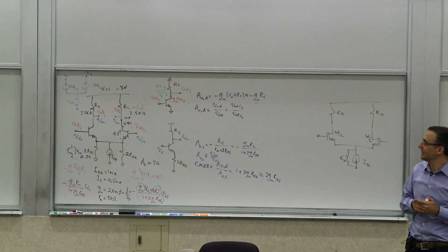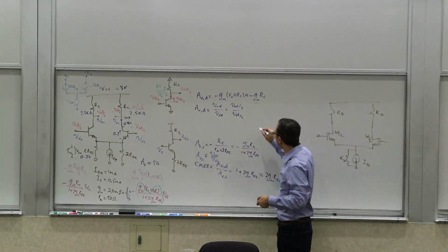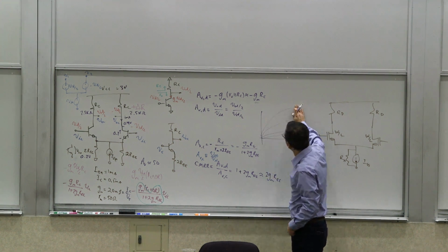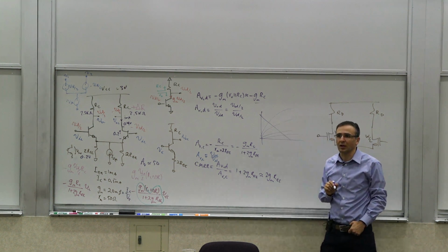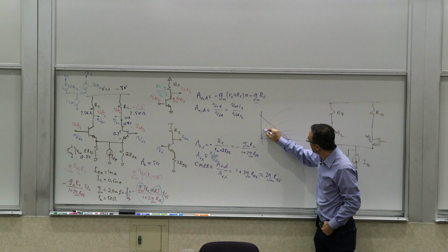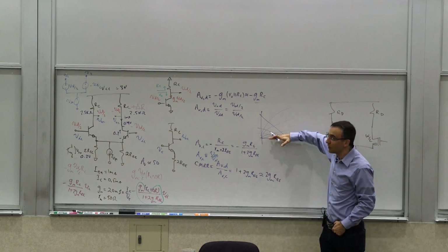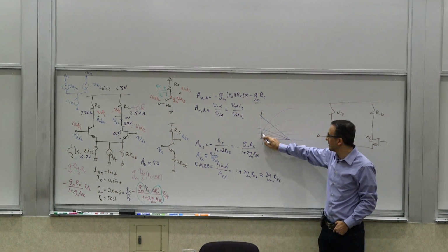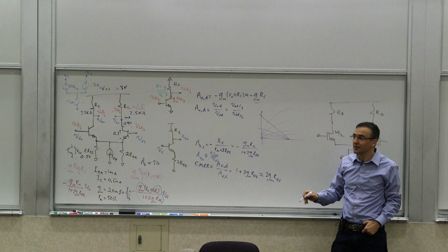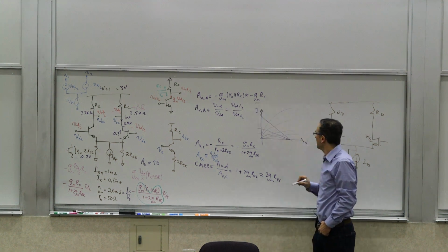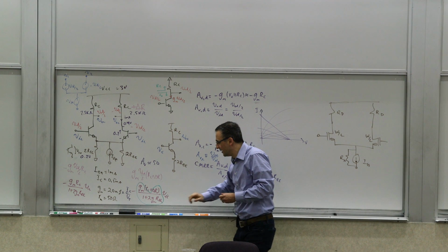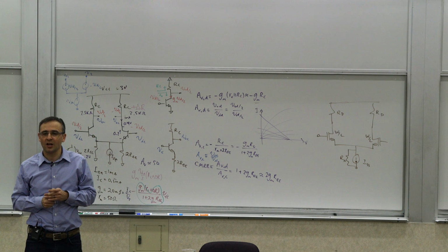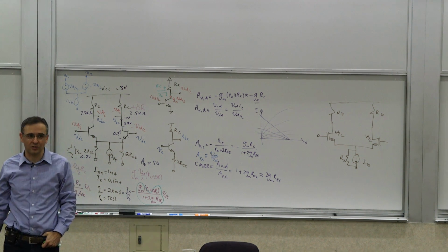What is it? Ideally, you can think about it also in terms of load lines. We talked about this, right? If you look at this IV characteristic for MOSFET or bipolar, it doesn't matter. Basically, this kind of load represents this kind of load line. And as you increase R, you're making it shallower and shallower. Yes, you're getting more and more slope, where you get more variations on the output, but you're getting less and less current, because you're increasing the resistance, right? This is I versus V. So what kind of load lines do you like? You want something that's more horizontal, something that can maintain current, but does not have a lot of fluctuations, which is basically a current source.